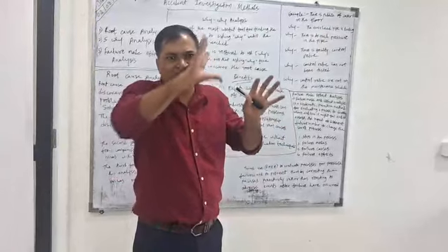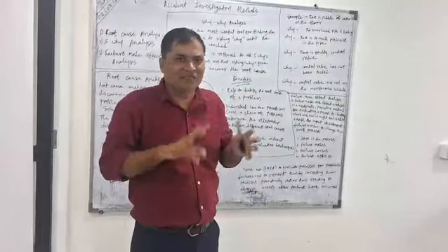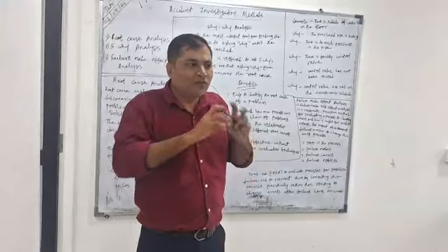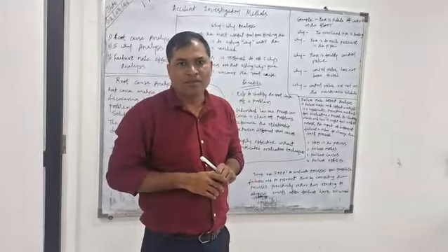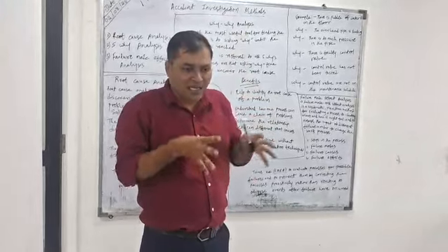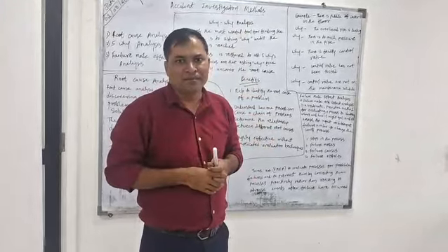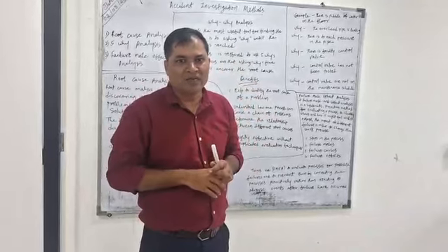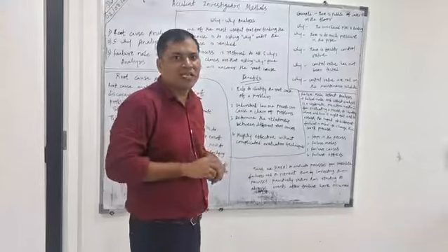So many valves we have in companies, so many pressure gauges related to the pipelines, pump rooms. Okay, so you have to check the pressure flow. Is the pressure flow high or maybe low? If you are working as a fireman, you have to go continuously to watch the pressure of water. Okay, maybe 9 to 10 bar. So these are the things which are very important.